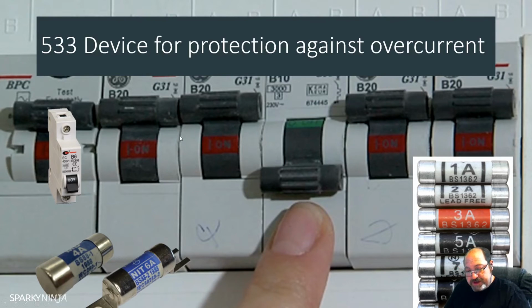And then it says fuses. A fuse shall be arranged so as to exclude the possibility of the fuse carrier making contact between conductive parts belonging to two adjacent fuse bases. So there'll be no potential contact between two adjacent fuse bases. That makes a lot of sense. A fuse base using a screw-in fuse shall be connected so that the center contact is connected to the conductor from the supply and the shell contact is connected to the conductor to the load.